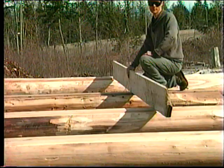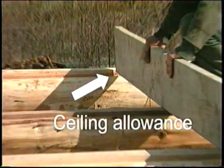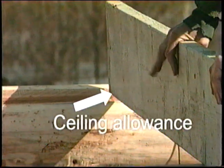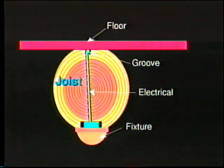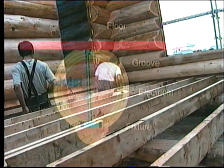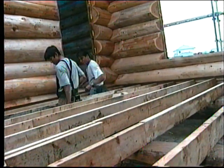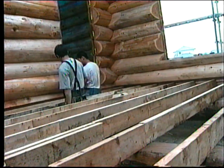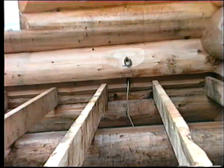A recess for the ceiling material can be dadoed into the edge of the beam or a furring strip secured to the top. If the ceiling is to be decked with a planking material such as 2x6 or 2x8 tongue and groove, it can be an advantage to make a groove for electrical wiring. If you are going to run additional joists, the wires can be run between these.